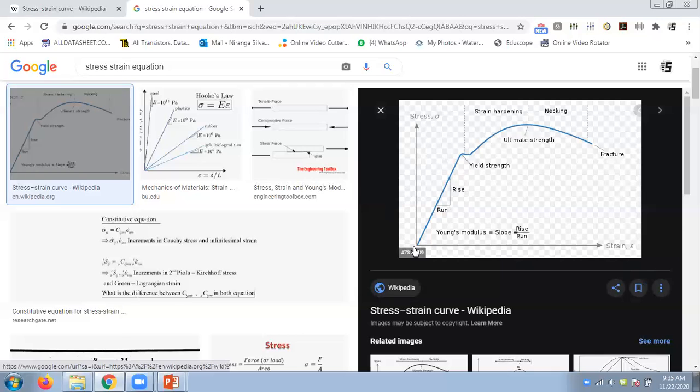When you apply a load and then release it, your model should come back to the normal position. Like a rubber tape: if you stretch it and release it, it should come back to the original size. If it does not, it has permanently gone into the plastic area and is permanently deformed. And if you apply a lot of load, ultimately it will fracture and break.